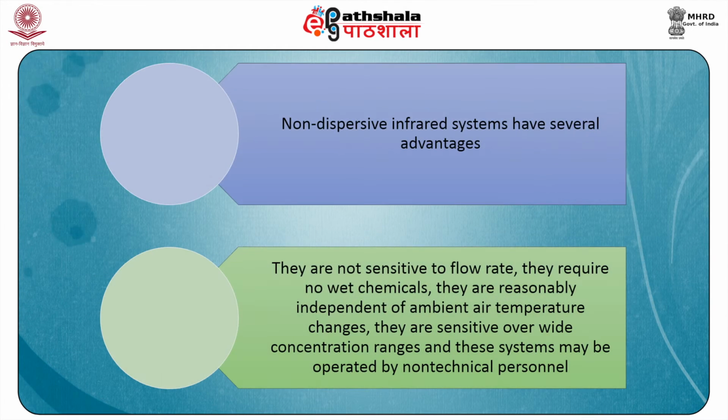Non-dispersive infrared systems have several advantages. They are not sensitive to flow rate, they require no wet chemicals, and they are reasonably independent of ambient air temperature changes. They are sensitive over wide concentration ranges, and these systems may be operated by non-technical personnel.